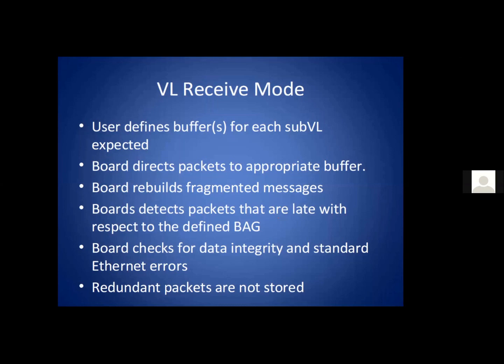So now the board does rebuild fragments into messages, and will only report to the user that it has a message when all the fragments have come in and the message is complete, because there's not much you can do with a partial message. There are also various errors that we'll detect. If you define the VL is supposed to come in every 8 milliseconds, and it came in after 10 milliseconds, we'll tell you this one was late.